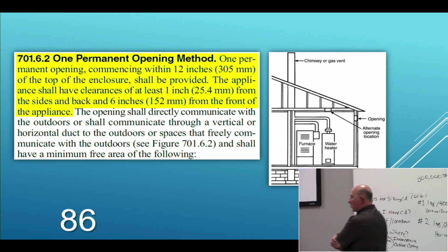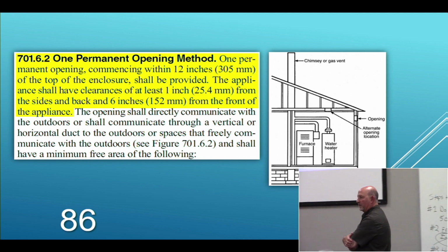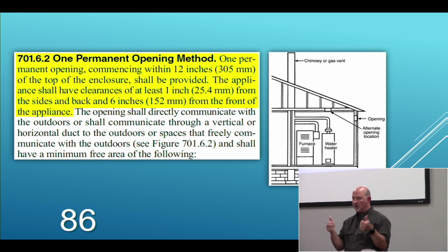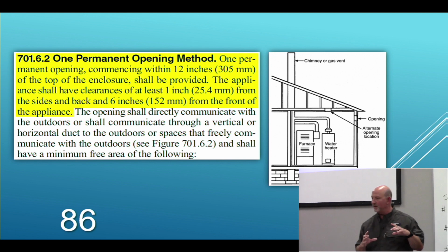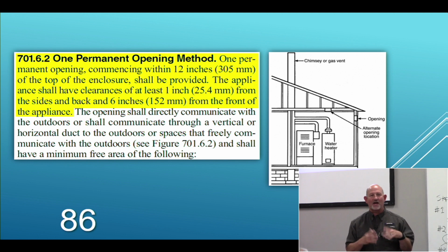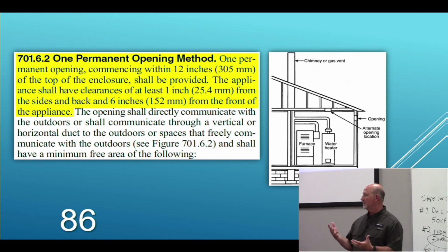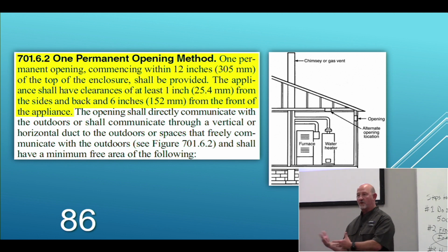And again, I'm okay putting a smaller drain line in there as long as it's still code, as long as I'm still meeting code, right? Now, just so you know, if I was plumbing my personal house, I might put a bigger drain line in there because I don't want problems for myself later. But again, legal, safe, code compliant. By the way, do you agree if those smaller pipes back up all the time, that would not be safe? Agreed? Code would not allow that. So again, they are still working the way they're supposed to work, right?